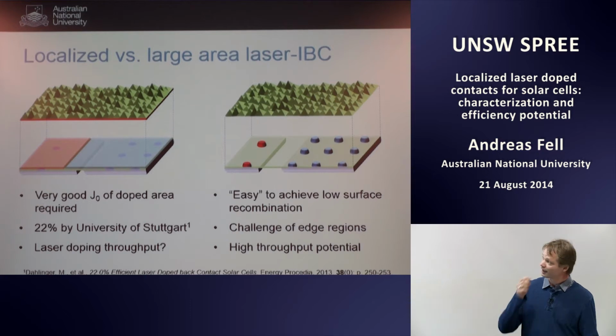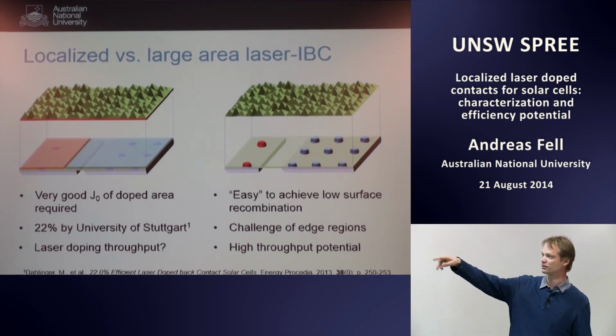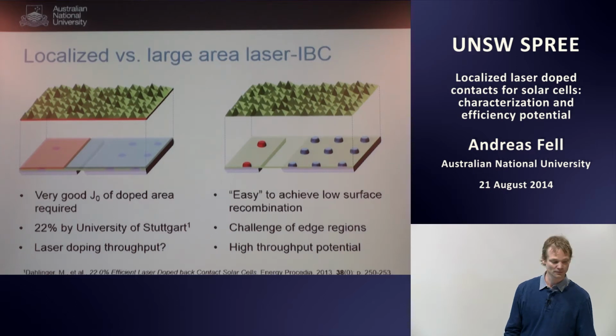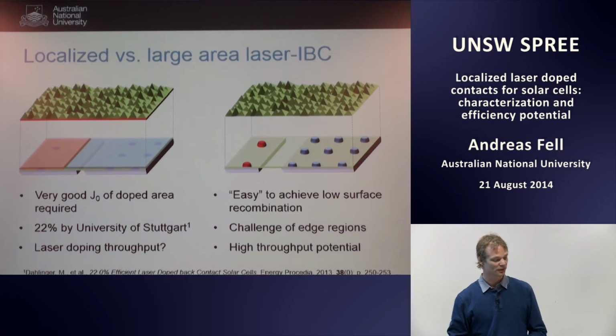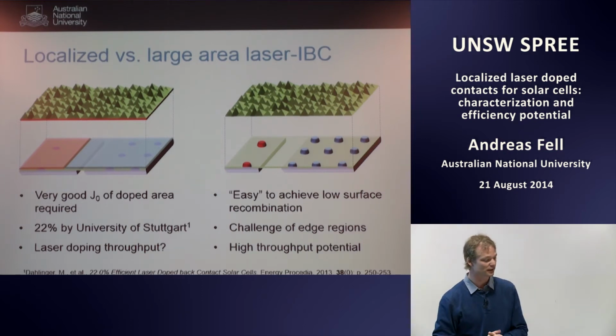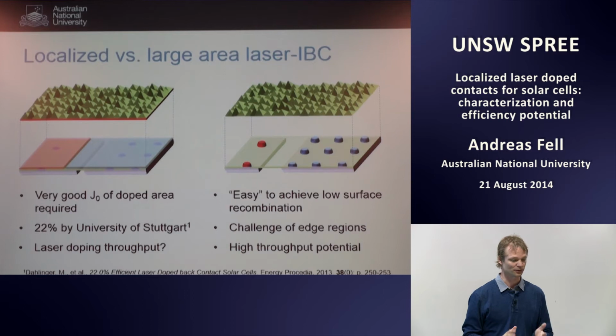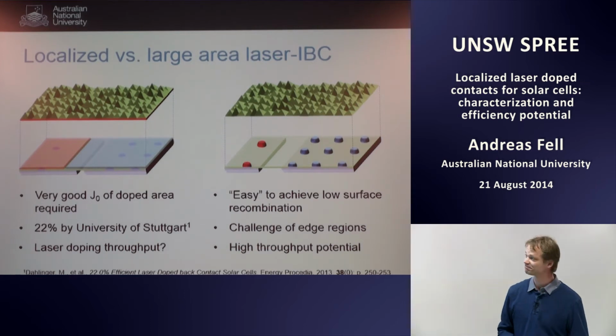And I believe that the final efficiency of such a concept should also be higher when you involve laser doping, because it's just too challenging to create excellent doped regions with the laser. I have to also say that on the left-hand side they use thermal oxidation for passivation, which has quite an annealing effect, and might be also questionable whether industry wants to do that.